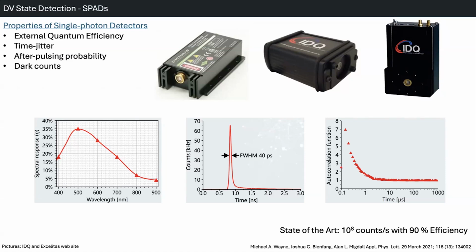For example, if you buy a single photon detector based on indium gallium arsenide technology, which is commonly used for infrared now, their dark count rate will be, I don't know, 10 times worse than silicon, which is 100 times worse than the superconductor detectors, which cannot be used for quantum computing at the moment. I see. Okay, thank you for the information.